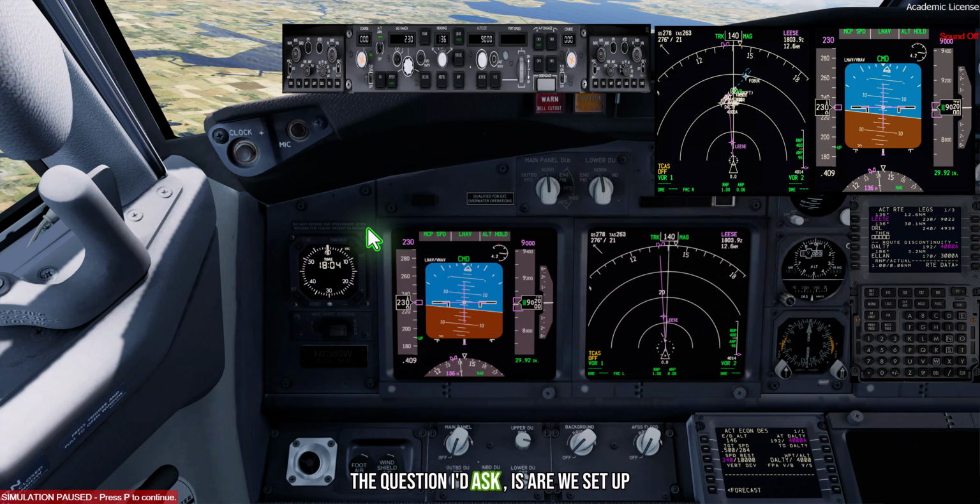And the question I'd ask is, are we set up with the system to be fully operable in the FMC with the lateral navigation and the vertical navigation? As I look at my FMA, I should be able to tell that. And that's not the case because we have, instead of FMC speed, we have MCP speed here.